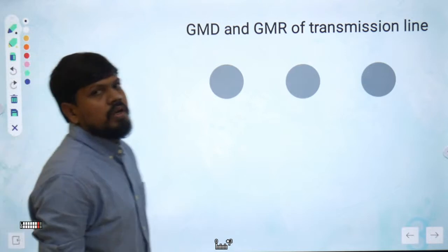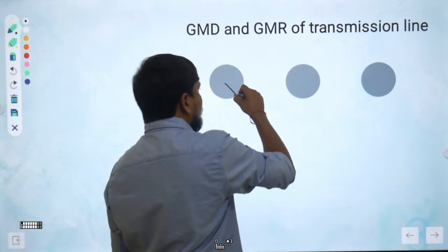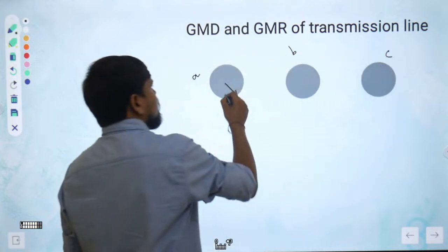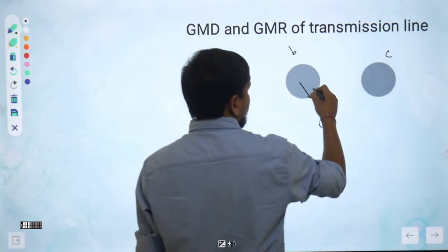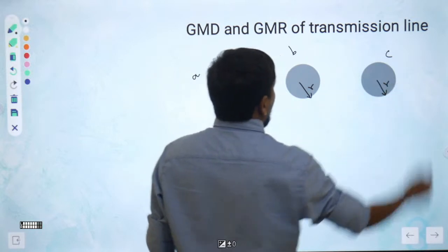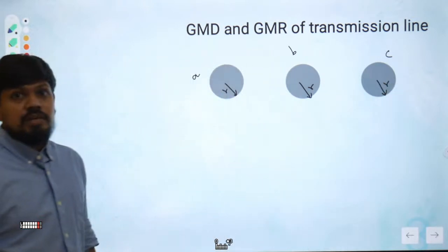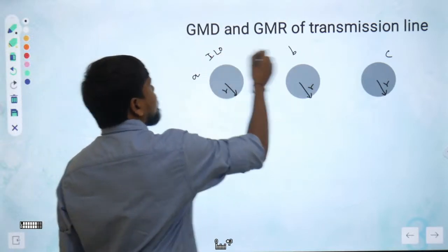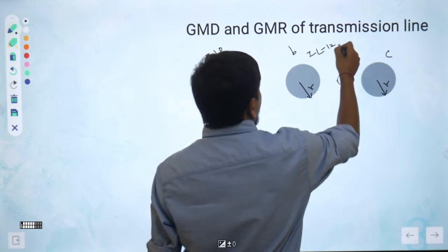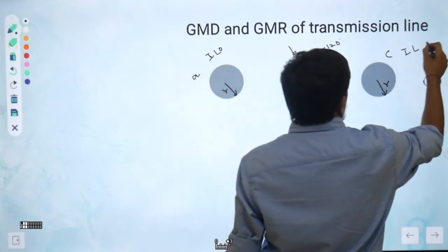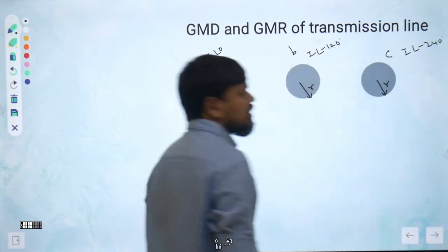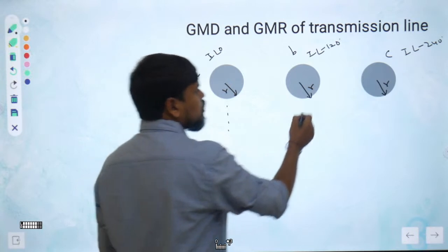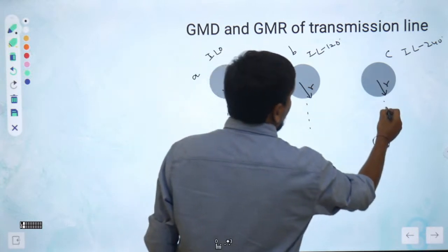Okay, so that's all. Anyway, you just see, if this is the three phase system, which is A phase, B phase and C phase, this is the radius R and this is the radius R and this is the radius R, because all the three phases are balanced now. So balanced current only you will be preferring. I at an angle of 0, I at an angle of minus 120, I at an angle of minus 240. So these are the three currents. And anyway, distance between the conductors, let's take from center to center only. So that is the distance you will be considering.